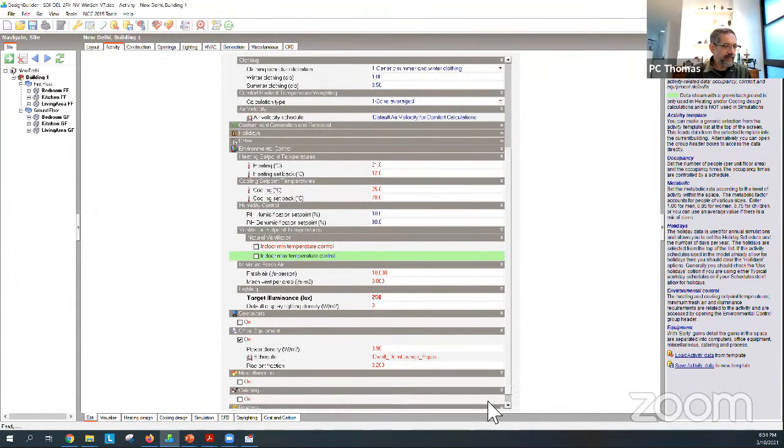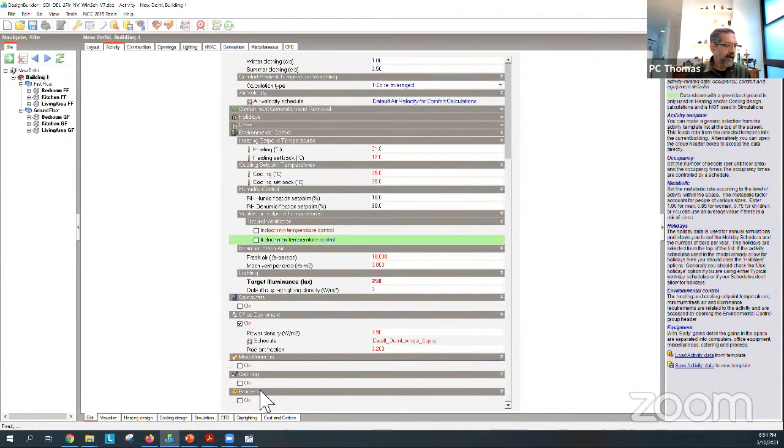After this, you'll find that there are 5 ways that you can give other heating systems. So you can say computers or office or miscellaneous or catering or process, or any combination of 2 of the 5, right? Typically, we will leave only 1. In this case, I've called it office equipment.